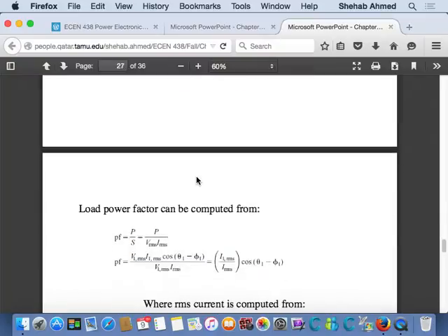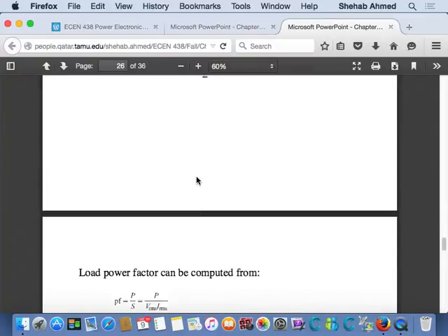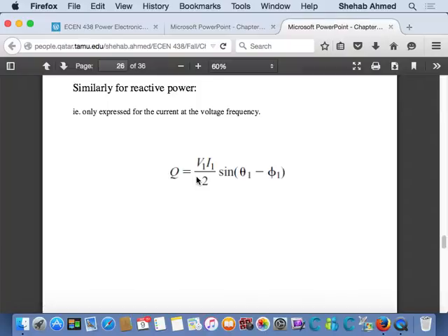So we have to account for this other stuff, though, right? This is current flowing in the system. These are extra currents, harmonic currents flowing in the system. And we said that we rate our equipment based on what? How do you rate your transformer? Do we rate it only based on the amount of real power transferred, or average reactive power? Apparent power. And apparent power has to include all harmonics, all the voltage and its harmonics, all the current and its harmonics. It's the multiplication of the total VRMS and IRMS, including VRMS fundamental, second, third, for all of these things.